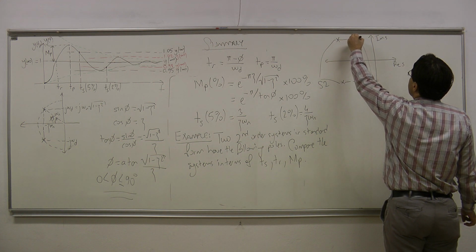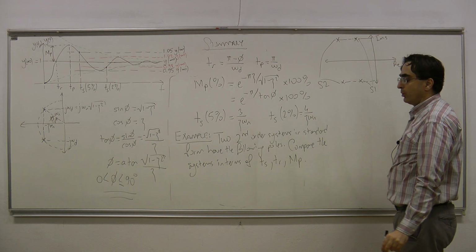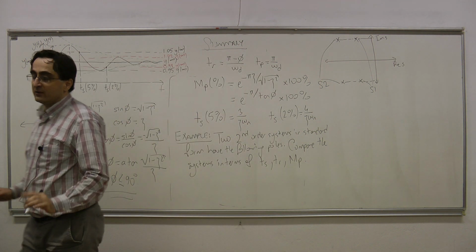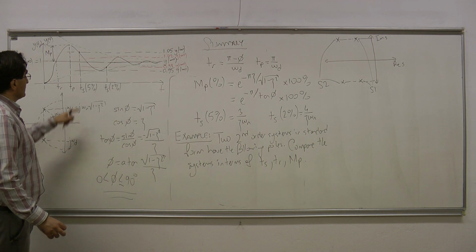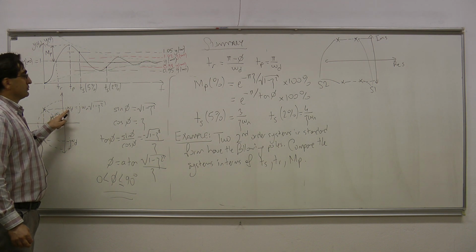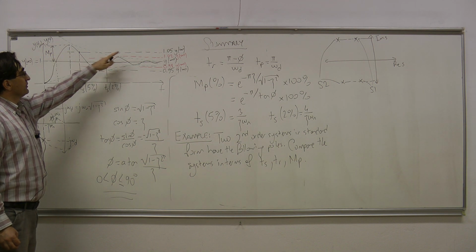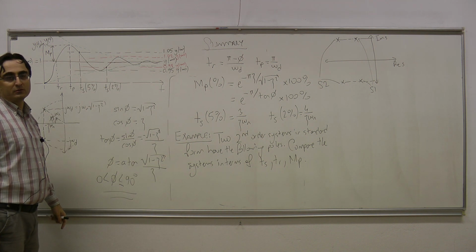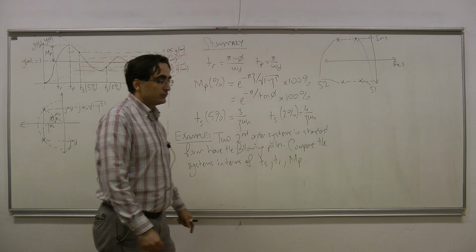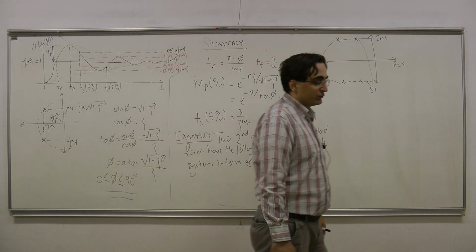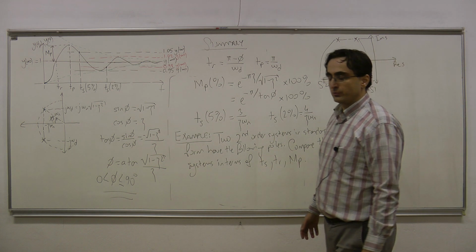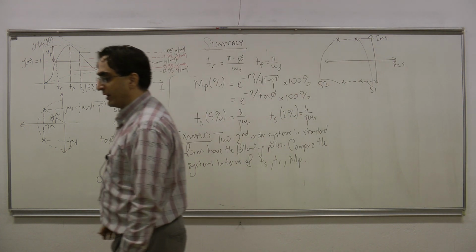We see that the imaginary parts of the poles are the same for these two systems. What does that mean? We know that the imaginary parts of the poles are determining the frequency of oscillations in an underdamped response. Okay? So if I try to draw the step responses of these two systems, then the frequency of oscillations of those two responses should be the same.